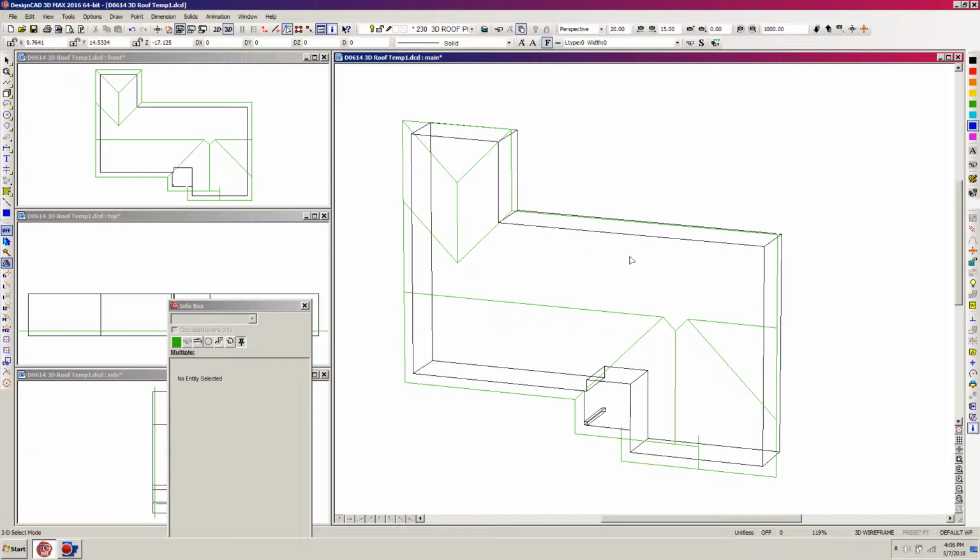So now I can start on my roof plane. The first one I'm going to do is this primary one back here on the back. So I'm hitting P, and I'm right clicking here. Then I'm hitting H for orthogonal mode and coming all the way over to the side here and hitting K. And now I'm hitting H to go out of orthogonal mode and gravity move.